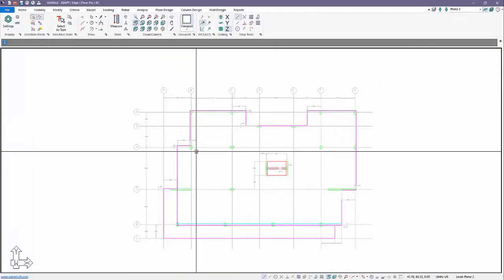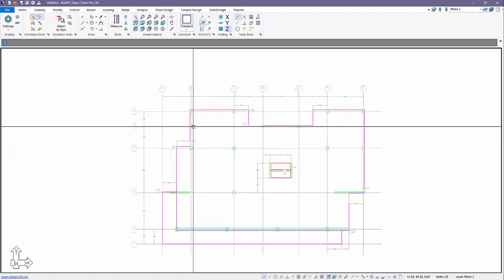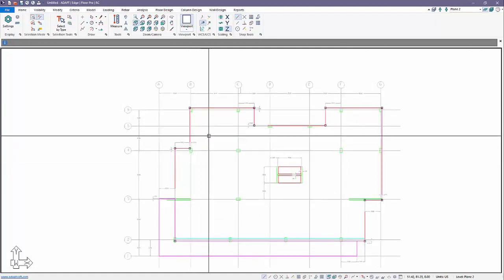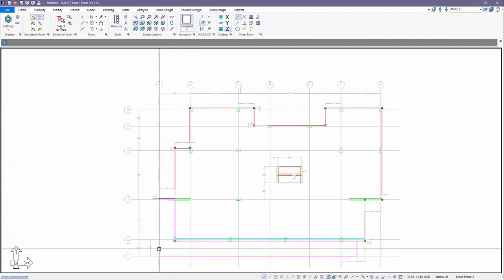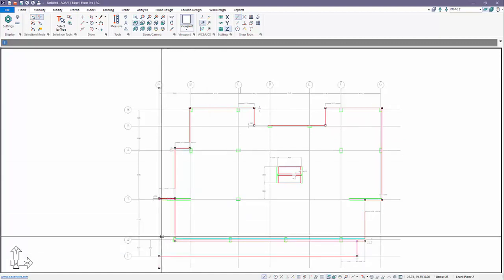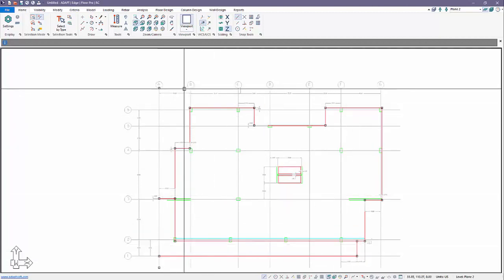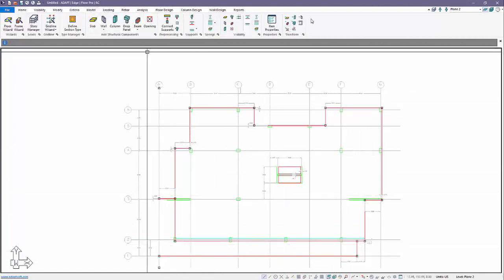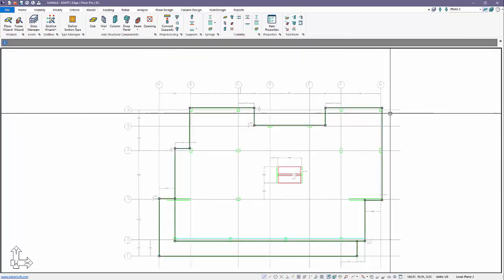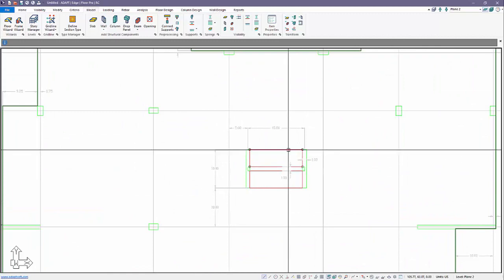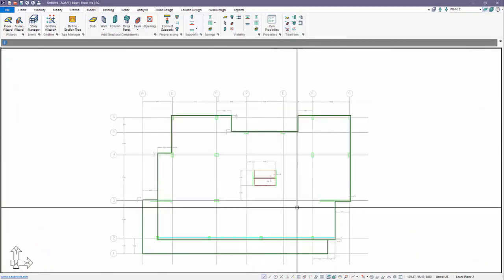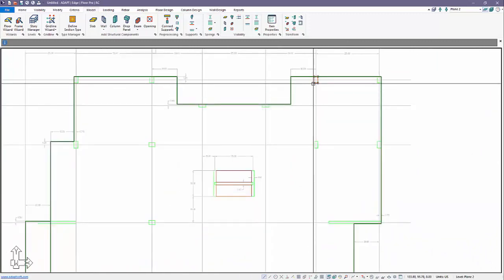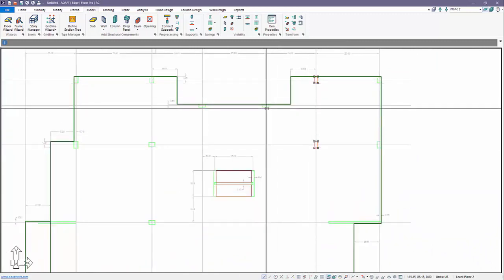The next thing we're going to do is we're going to transform components into polygons. So I'll select polygons. The slab, for example, is a polygon. This slab is also a polygon, so we'll select this slab and this slab. We have 2 slab regions. We're going to go over to Model. On the far right end, we have the Transform panel, and I'll transform these into slabs. I'll now transform openings in a similar manner. We'll use the Openings option, and we'll just work through the model, transforming these different components.